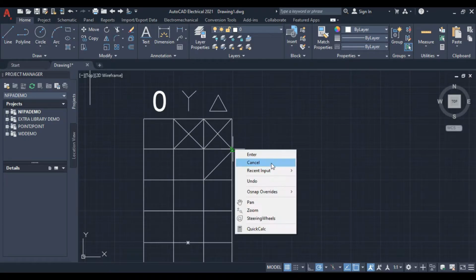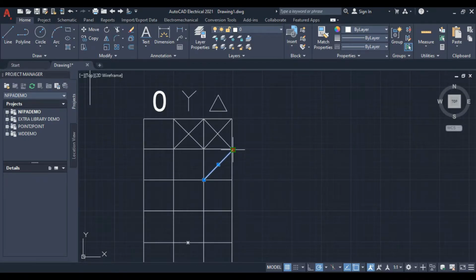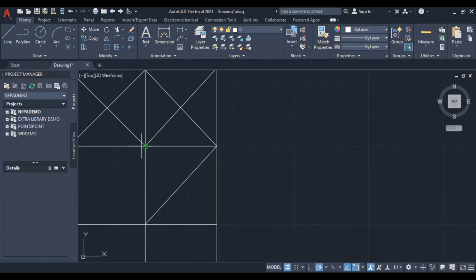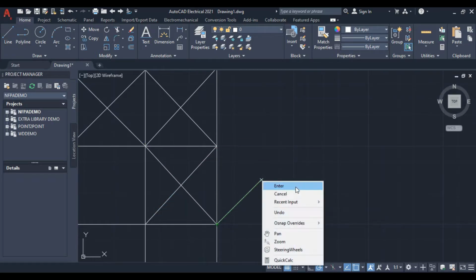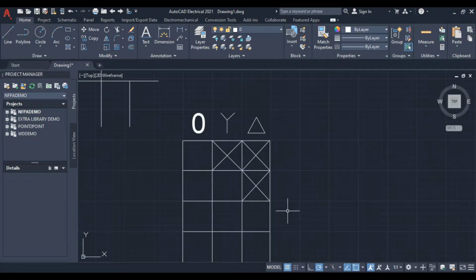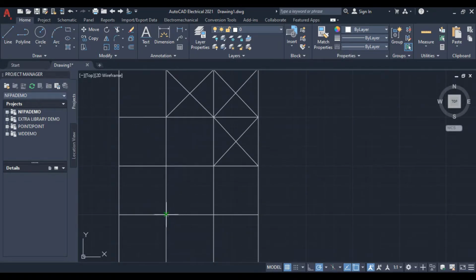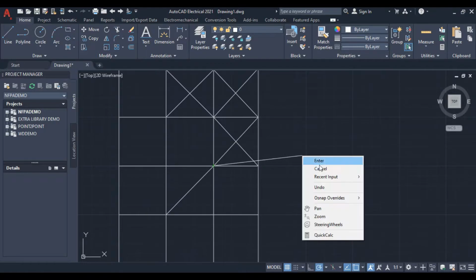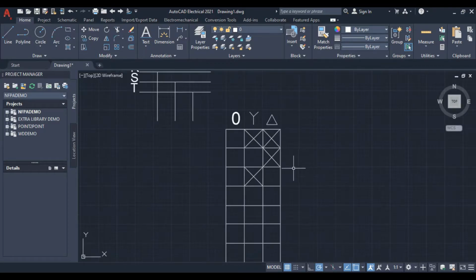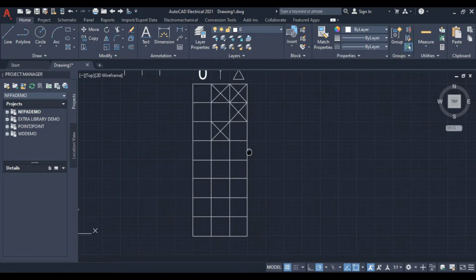and in the delta and star connection system, there is no need that you do it by hand or by cables at the end of your electromotor, X, Y and Z. For example, you would need to connect 3 cables at the end of a 3-phase motor to determine if it is delta or star. But in here, you can do it simply by this 3-phase key, and it will do the job.